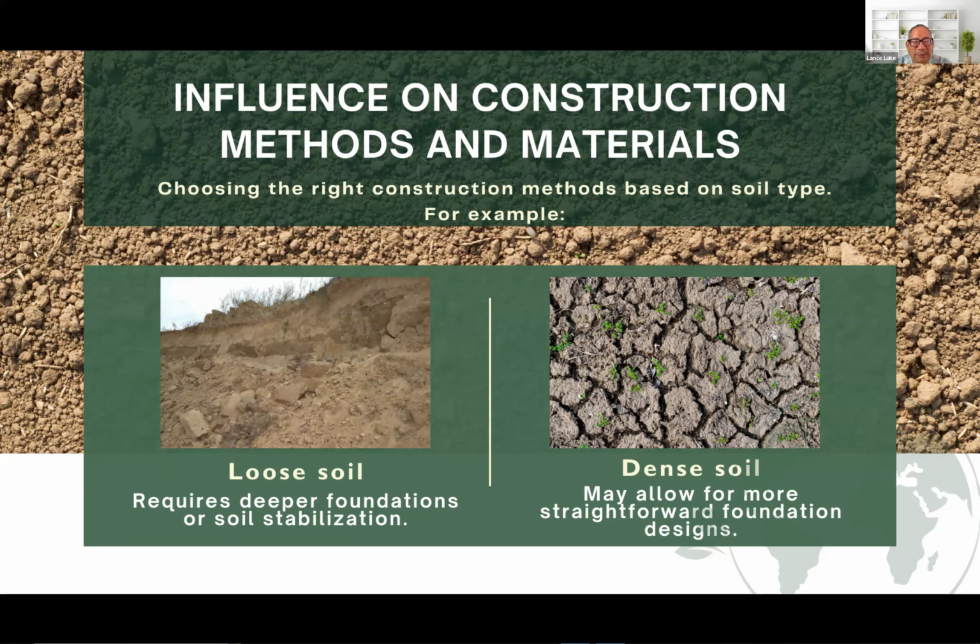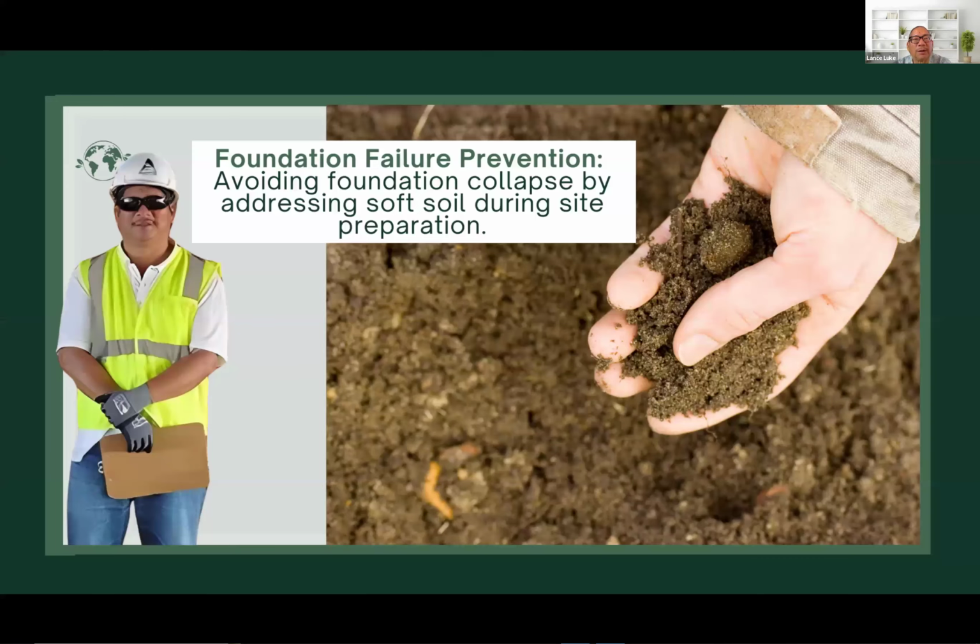The loose soil requires deeper or reinforced foundations such as piles to prevent settling. The dense soil allows for simpler, shallow foundations, potentially reducing costs. Material selection: soil stability affects the choice of materials, like using moisture-resistant materials in clay-rich areas. Okay, so that's the difference.